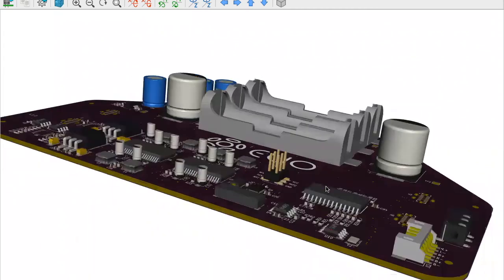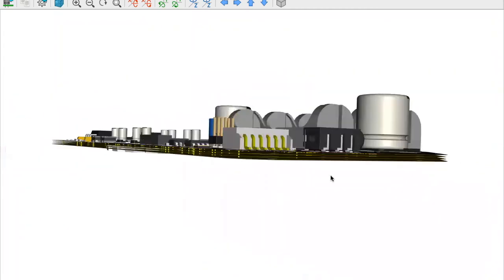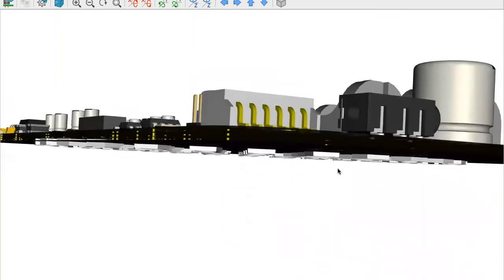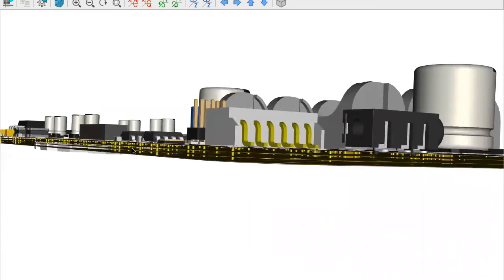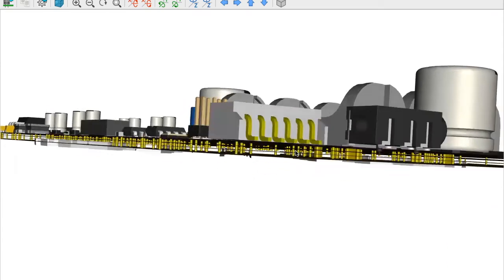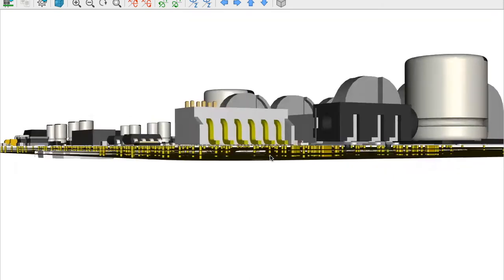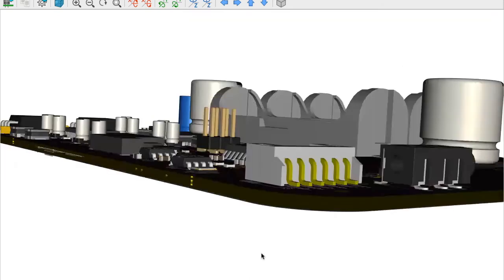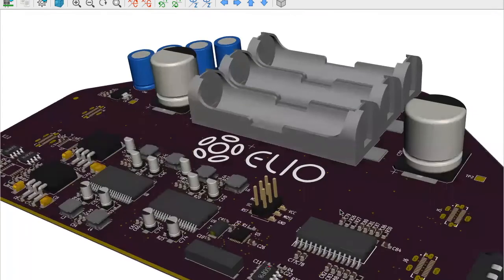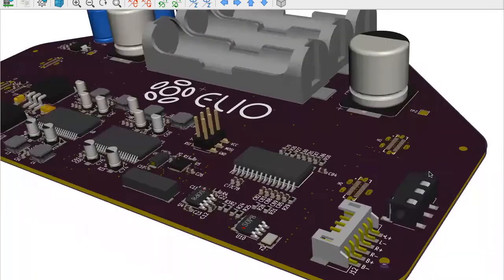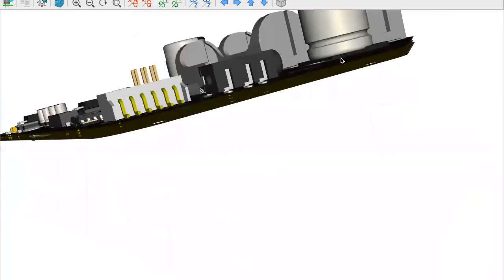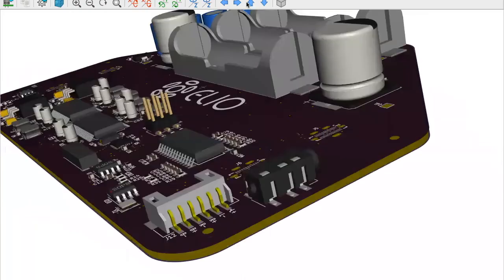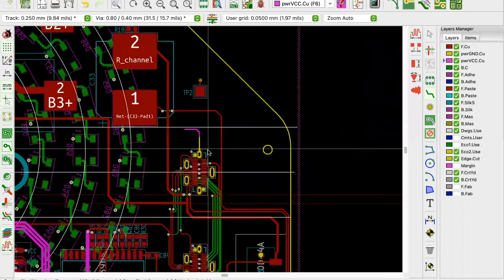So once I uncheck that, you realize that now in KiCad you can see inside how we see the layers, the vias, and how they are interconnecting. You see here inside. So when you disable that feature, you are able to see how things are connecting. And if we go to where we did the buried via, or let's do this, we can move it somewhere closer at the edge so that you can see how it runs.